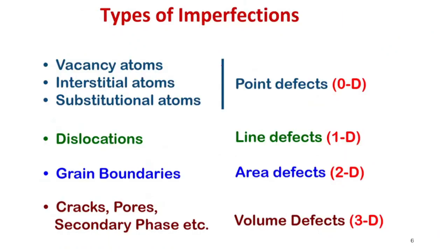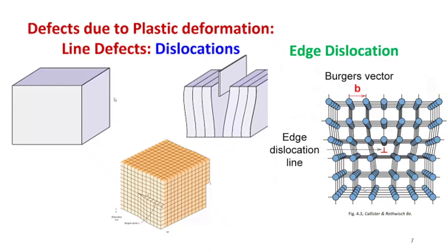This we already saw, the types of imperfections. Now coming to line defects. We have a crystalline lattice like this, and a plane is inserted. Usually these line defects or dislocations don't happen just because some plane is inserted like that. This is due to shear stress. When we give shear stress, certain bonds tend to break, and when a bond breaks, there will be an extra half plane.